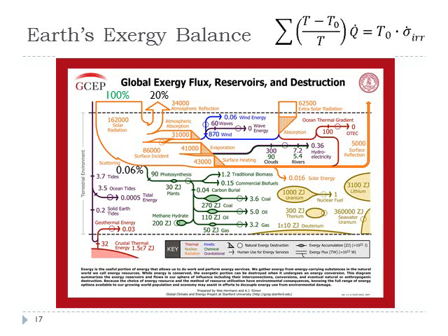So we could calculate, if we wanted, the amount of irreversibility occurring on the Earth if we knew the amount of Q dot and the temperature associated with the Q dot. So if we assume all the Q dot is leaving at the temperature of the Earth, T is equal to T naught in that case, right? So that term actually would drop out.